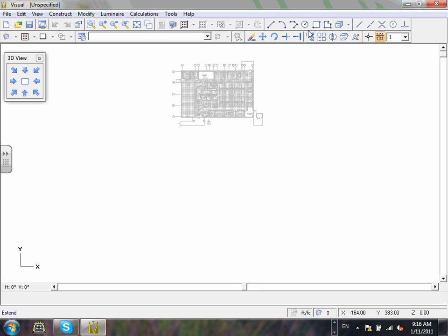Here's the interface. There's an interface like copy here. This is delete, erase. Can you guys see that? Erase, move. This will be rotate, trim. If you need to trim. The most important one, guys, is probably move. You're going to be moving a couple of things. So I'm going to hit move. Everybody with me? I'm going to hit move, and I'm going to highlight like in CAD, right to left to right. I'm going to highlight everything here.